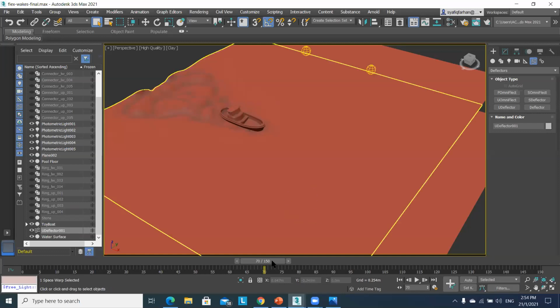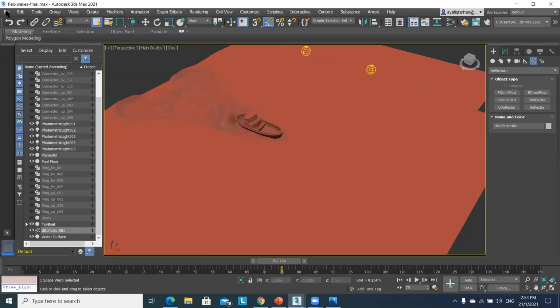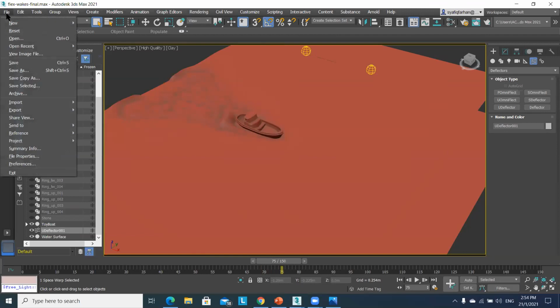That will be the benefit when you transfer your 3D modeling from Revit or Inventor, just using this method, file. You can use import or link Revit here. Revit, you can directly import. For Inventor, you need to open your Inventor first and import your Inventor file before you start dealing with 3ds Max.